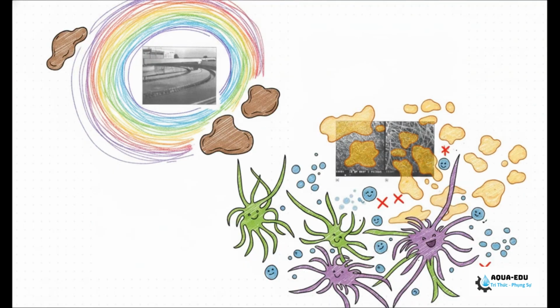Now, the very first step in any crisis is validating the severity by recognizing the physical symptoms right out there on the floor, because you obviously can't fix what you haven't diagnosed. Out in the clarifier basin, you might start noticing this thick rainbow film, or just chunks of floating brown grease. But when you get down to the microscopic level, the proof is right there. Our biomass is getting completely coated in a lipid layer. This physically blocks the exchange of oxygen and carbon dioxide, which causes the localized death of our good bacteria and simultaneously triggers this massive, explosive growth of oil-loving filamentous bacteria, like Nocardia.